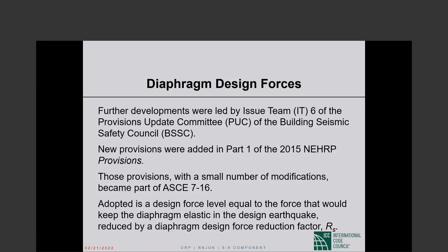In a beam column, is it required to design core? Yeah, this also you have covered. Can we consider slab on grade as a diaphragm if collector elements are inserted between slab on grade and column, but there is no connection between grade beams and slab on grade?